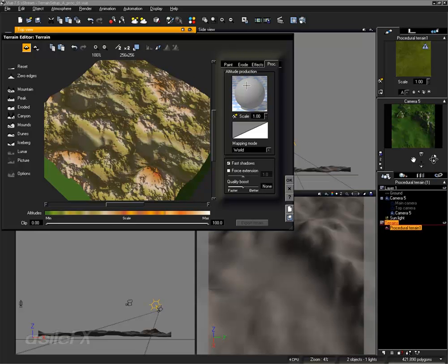So if I decide to move the camera to the left, what would happen, since the terrain is pretty confined to the space I currently have where the camera is showing, all I would need to do is either move the terrain within view, the camera view, or just stretch it out a little bit, scale it on the X and the Y, and an overall scale change of the terrain will not affect the Z as of version 7.